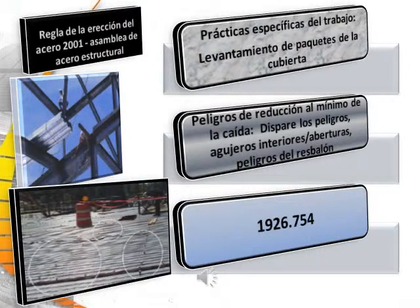The structural steel assembly section calls for specific work practices such as hoisting deck bundles, minimizing fall hazards, trip hazards, interior holes and openings, and slip hazards. This information is found under .754.